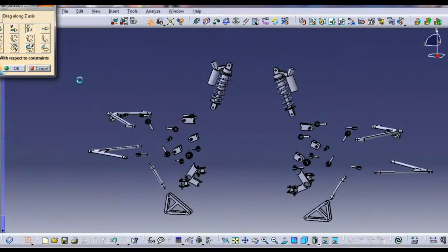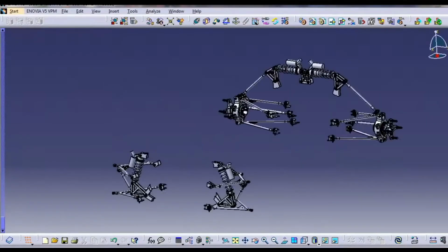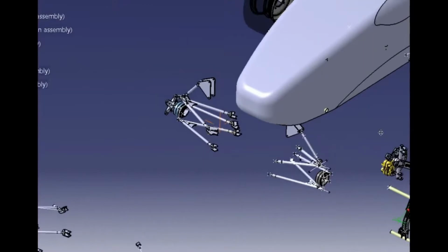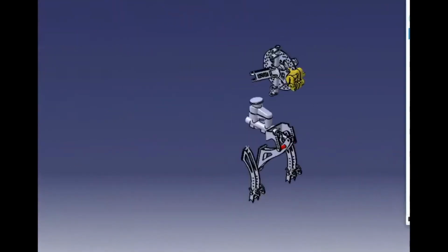As every system is interdependent, if any of the suspension parameters are changed, the steering also is affected, because steering and suspension share the same factors. Those are camber, caster, toe, KPI, scrub radius, etc. After seeing the steering and suspension system, now let's move on to the next one, which is brakes.